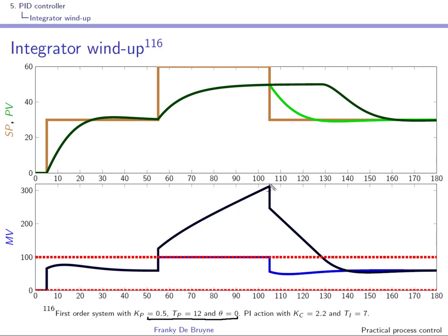Whereas with the badly implemented PI controller, the proportional kick is going in the right direction, right? But this is still far above 100, right? So you will not see any change on the actual process. It will still run the process with a fully open MV.